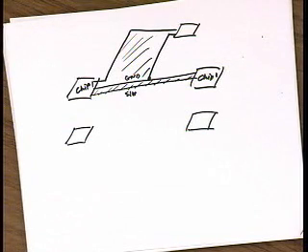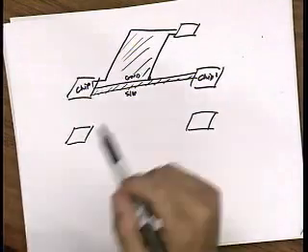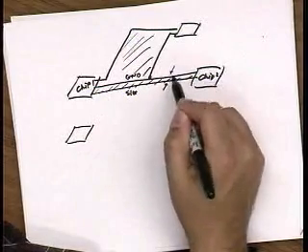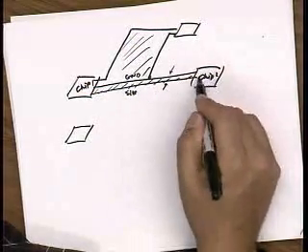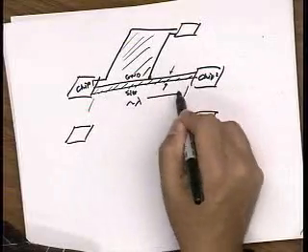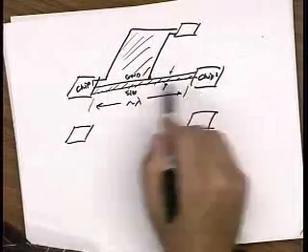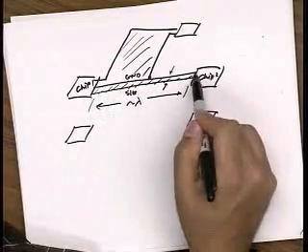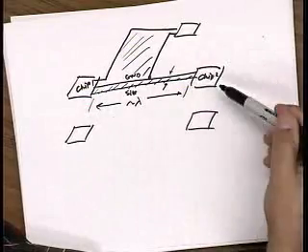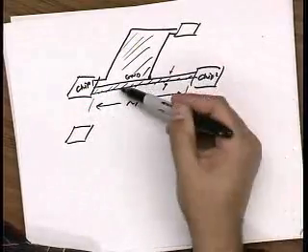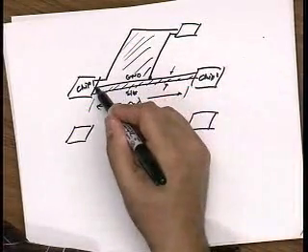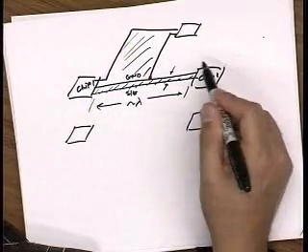Impedance matching. Why is that important? At high frequencies you see reflections maybe. Yeah, very good. So in this line there's a characteristic impedance, right? And it's determined by the spacing between these two wires. And if this structure is on the order of the wavelength, then I'm going to get transmission line effects. So if I send a signal on this end, let's say some data, when it reaches this end, if it doesn't see an impedance match, it actually will reflect. And at any given time, I'll be receiving a signal plus a signal that went back and reflected. And so I get intersymbol interference.